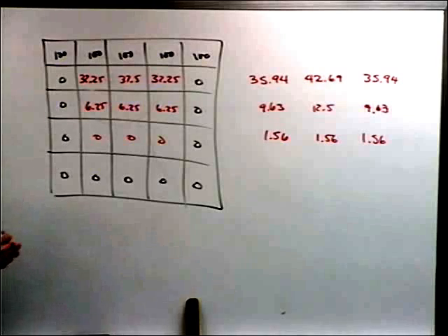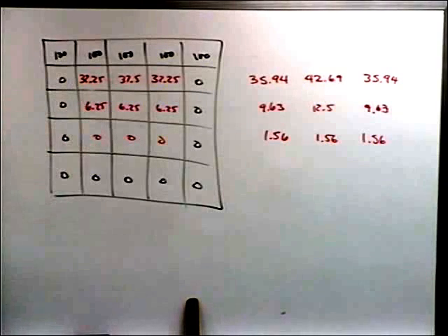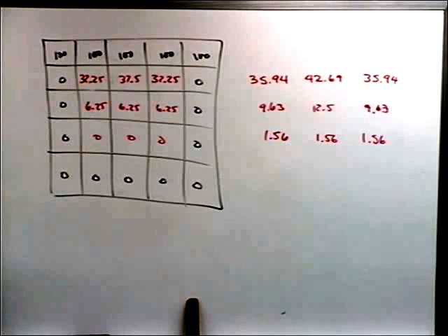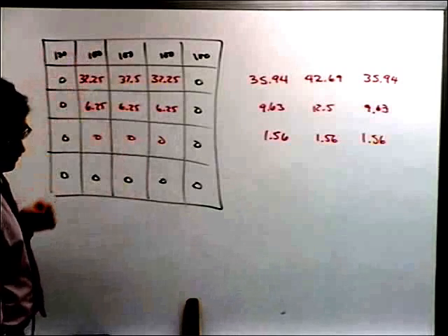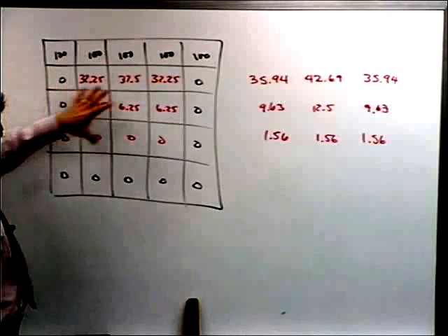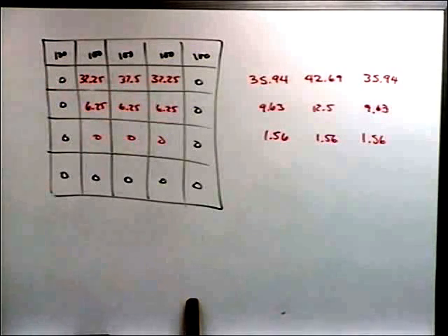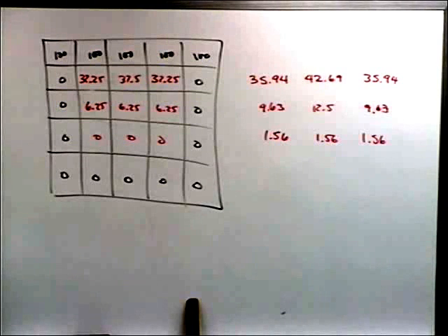Okay, so this is an example of a simple numerical technique, but it's one that you can work out almost on the back of an envelope, and it does give you a pretty good idea at least of how a voltage distribution is going to spread around. So there are problems where you might want to estimate the capacitance of something. You could solve Laplace's equation with some simple boundary conditions and get a pretty good insight into what that capacitance is going to be, for instance. So again, you'll talk about capacitance problems, I guess, Thursday this week.